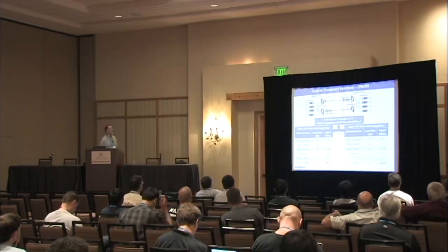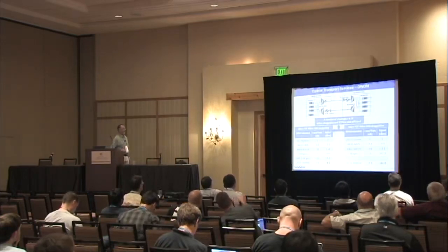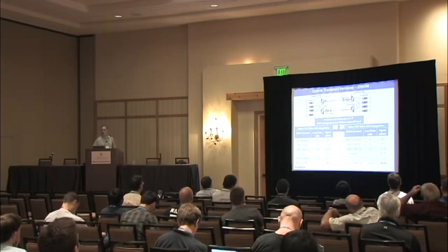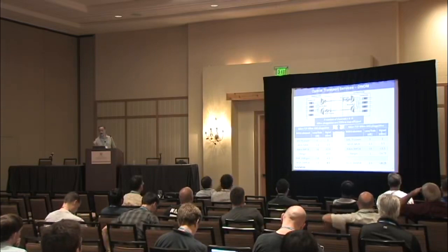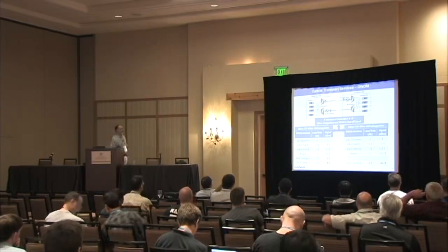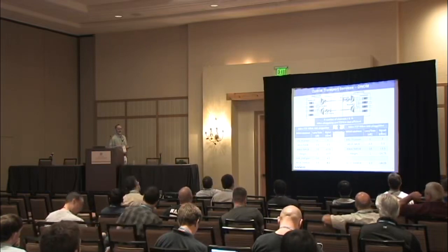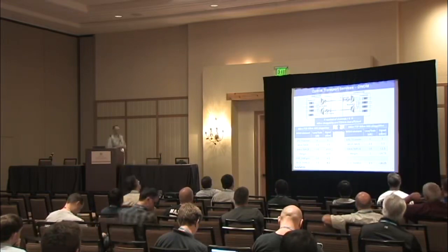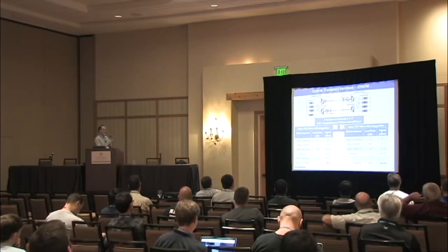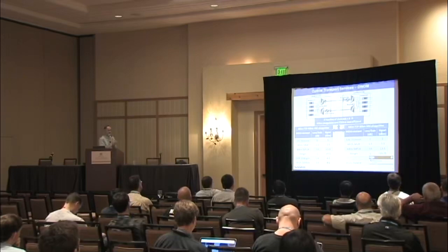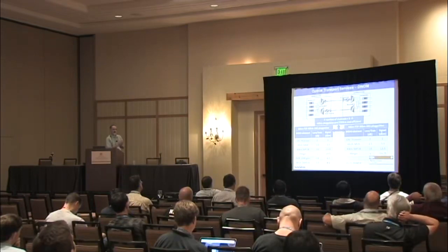Now let's look at implementing a 40 kilometer point-to-point using both 40 kilometer pluggables and 80 kilometer pluggables. Basically we have the choice of using cheaper optics and adding an amplifier, or using the more expensive optics. Same type of calculation. We start at 0. The Mux adds an attenuation of 3.5 dB. Then we have the 10 dB attenuation of the fiber. With a margin of 1 dB, I'm at minus 14.5, just adding all this.